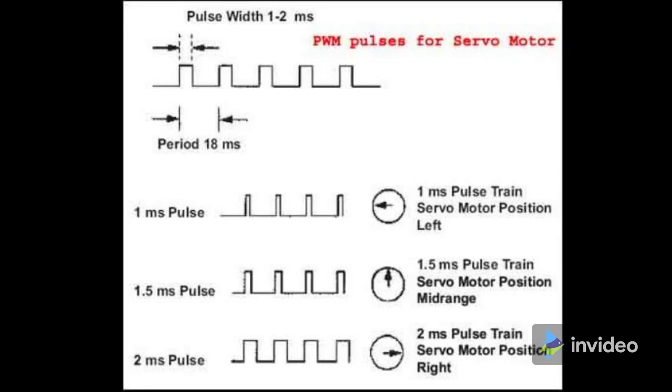When we press switch S2, the IC generates a short duration high pulse, which high pulse time would be equal to 0.693 × (R1 + R3) × C1, and low pulse time would be 0.693 × R3 × C1. Thus, in this case, the servo moves in the left, that is anti-clockwise direction.